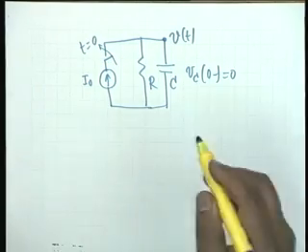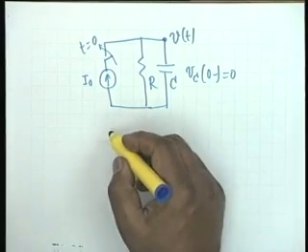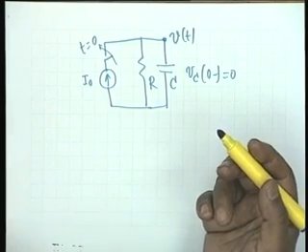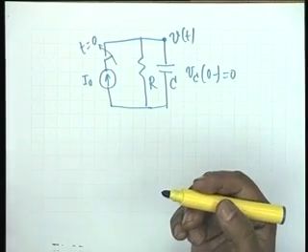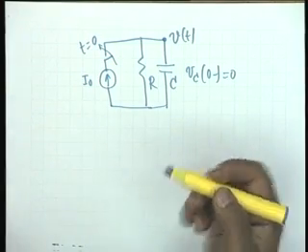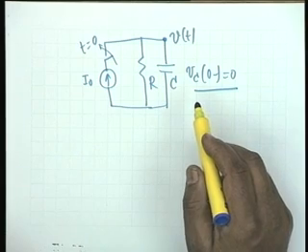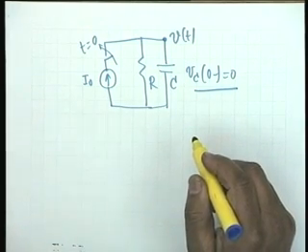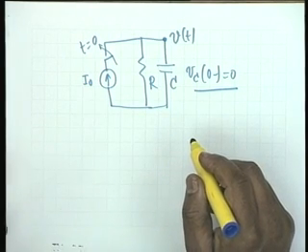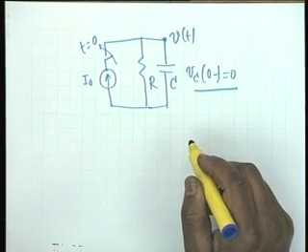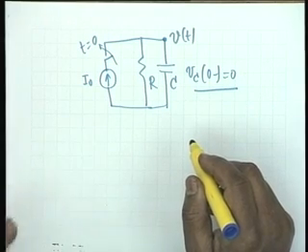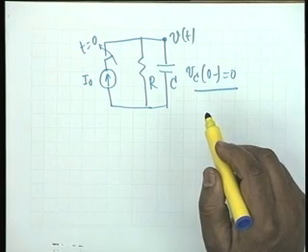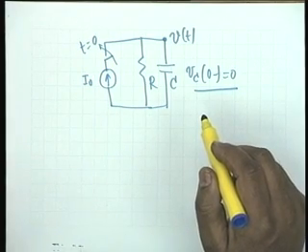That is a second type of response. I can either write the differential equation and solve it, or I can go directly into the Laplace domain, because the initial condition is 0. I do not have to write the differential equation, but mind you, if the initial condition is not equal to 0, then you must write the differential equation and take the Laplace transform term by term, because the initial condition term imposes the equivalent of a driving function.